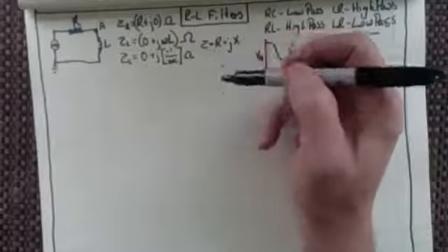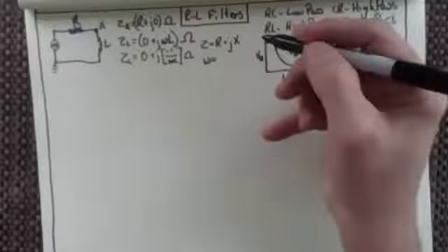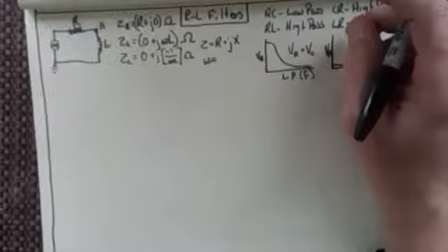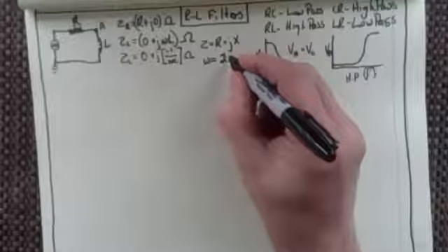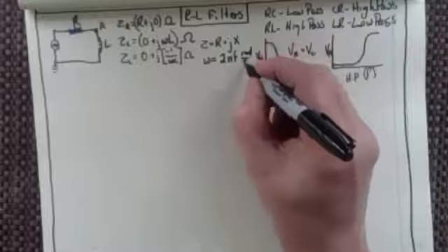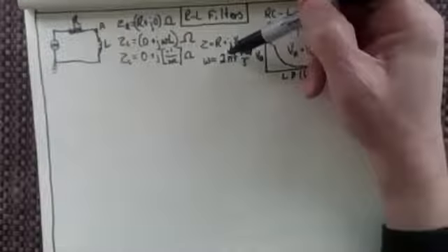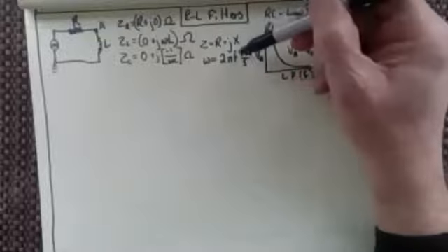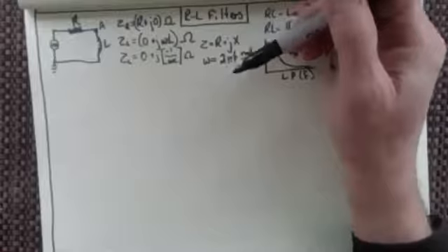All right. What is omega? I would call on somebody to give me that, but of course there's no calling on anybody here. So omega is 2 pi f, and of course those are radians per second. Remember how we got those radians per second. 2 pi radians per cycle times f, and f is cycles per second.